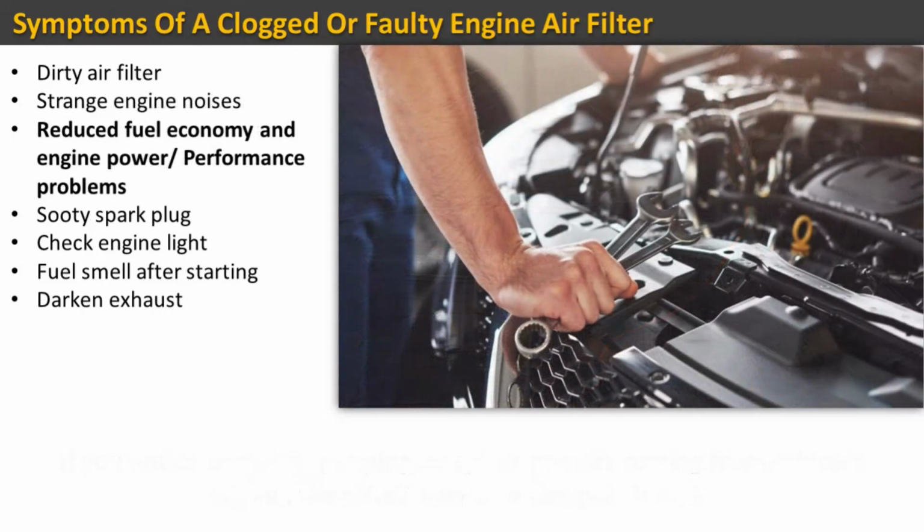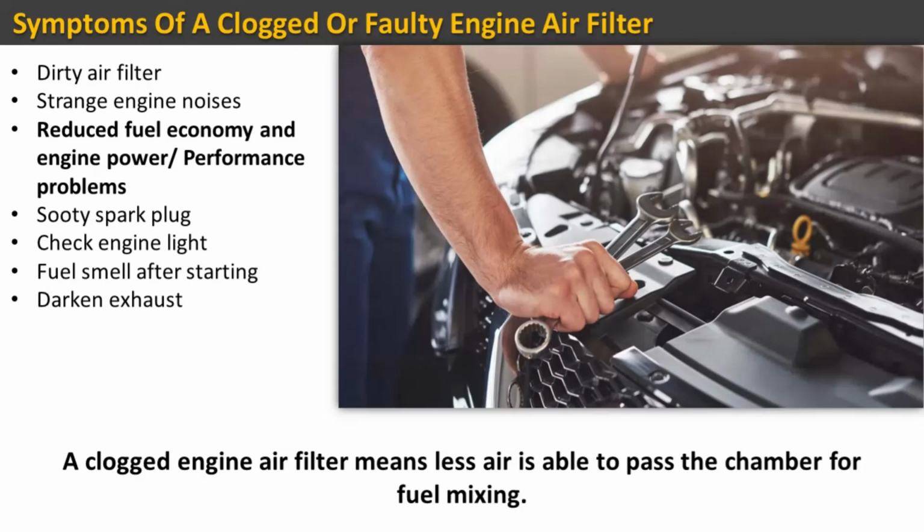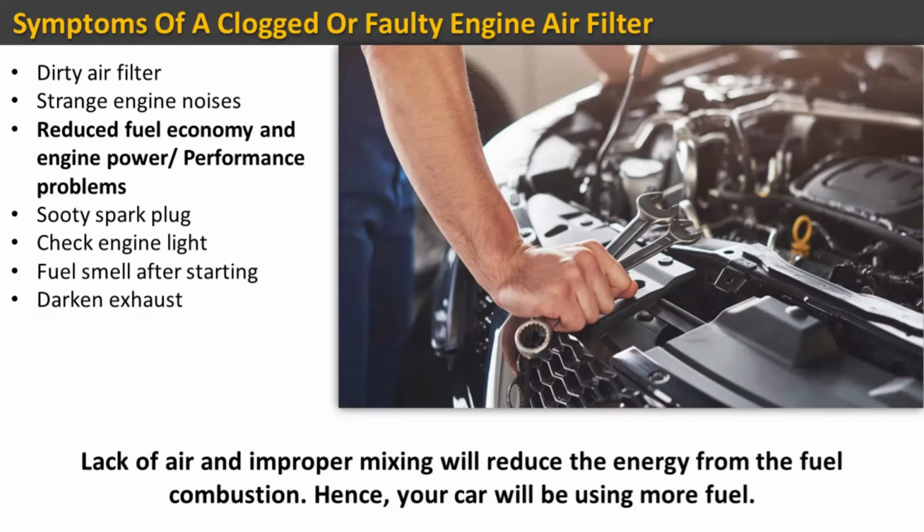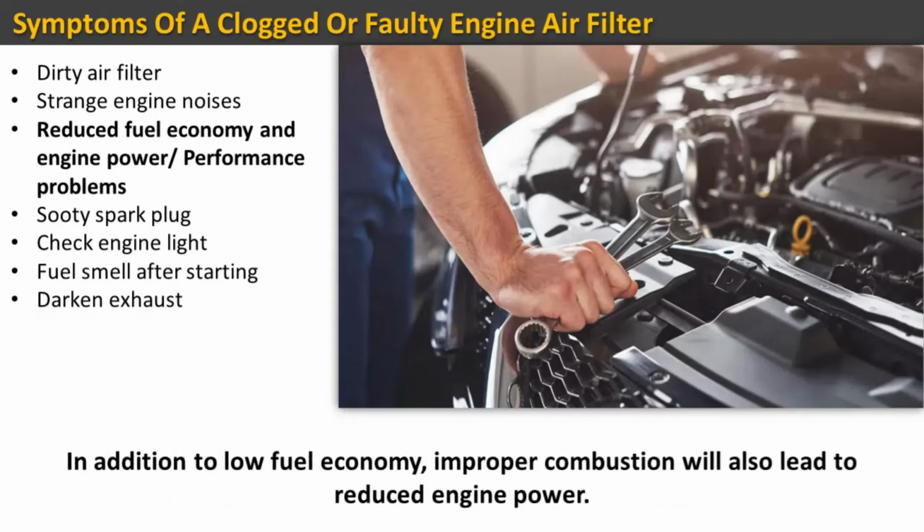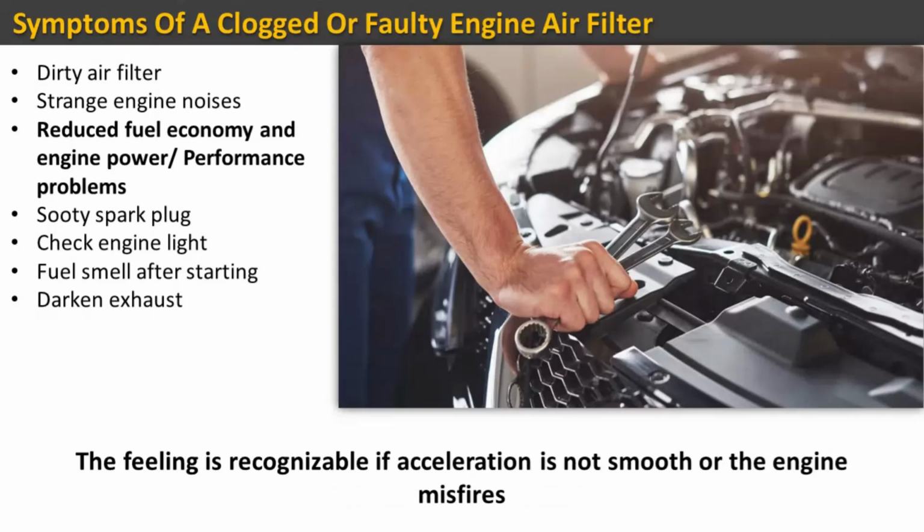Reduced fuel economy and engine power or performance problems. A clogged engine air filter means less air is able to pass to the chamber for fuel mixing. Lack of air and improper mixing will reduce the energy from the fuel combustion. Hence, your car will be using more fuel. In addition to low fuel economy, improper combustion will also lead to reduced engine power. The feeling is recognizable if acceleration is not smooth or the engine misfires.